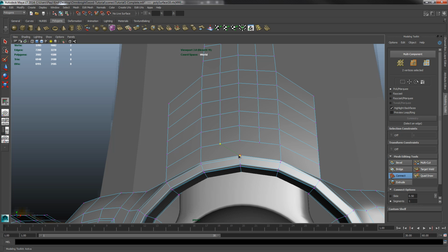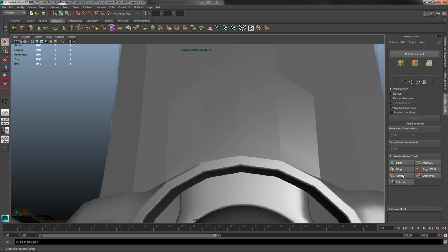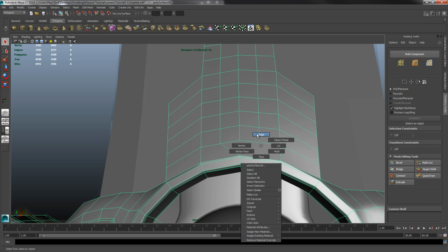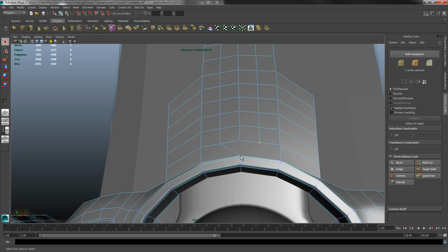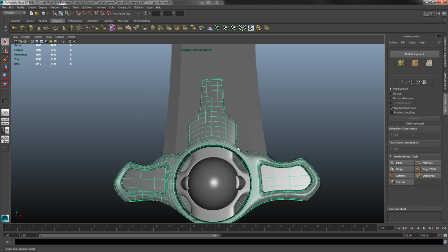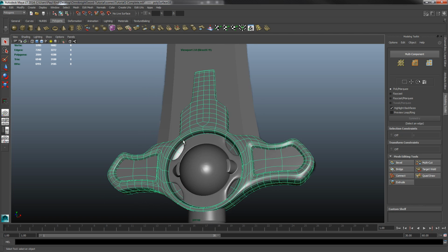And as you can see, when it's dealing in points, it's going to deal with it now as this type of a connection. Okay, so we're just going to go ahead and undo the connect. And now when we select our object, we'll see that we now have a connection line. So that's good. What we want to do now is just connect the other side. So I'm just going to go vertex again, select, and connect. And undo the connection. And now you should be back to where I am. Then when you hit 3, it'll all smooth beautifully, and you won't have any interruptions in that circle.